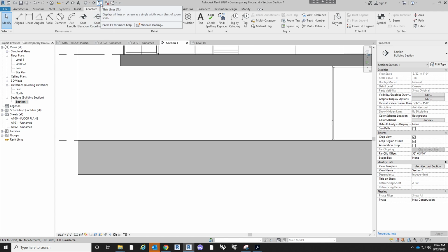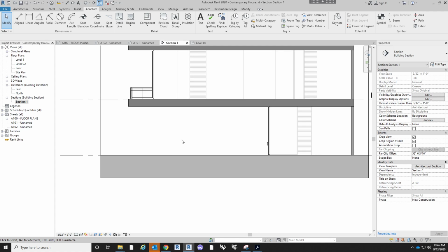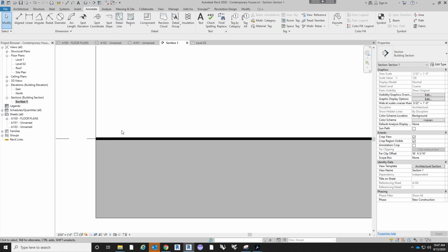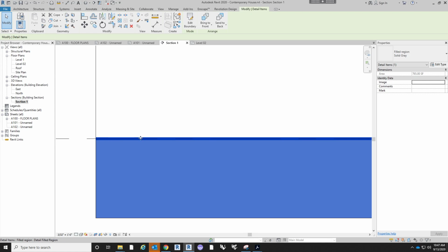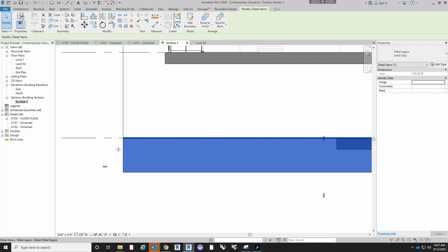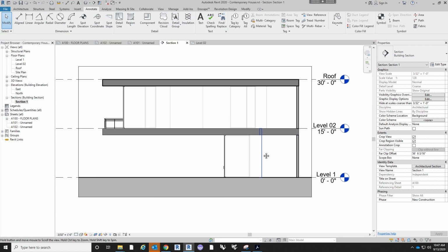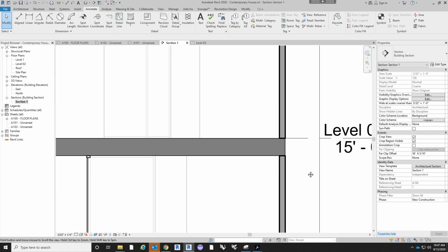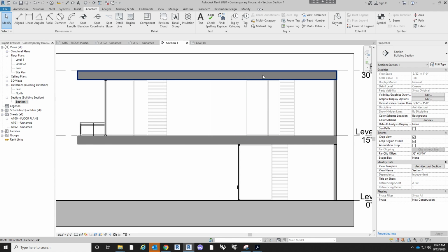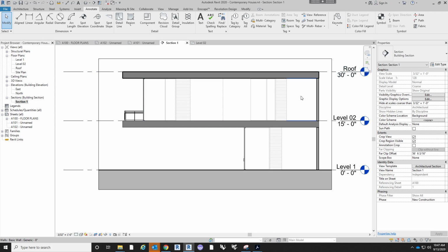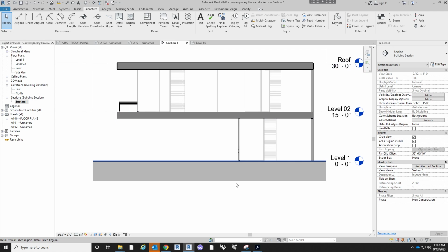the reason why we can't distinguish it right now is because we have our thin lines up at the top on to be able to distinguish between objects and have really nice crisp control over everything. But if we go up at the top to this thick line to thin line and uncheck that, you can see that the wide line that we just associated with the filled region is much thicker than the rest of the lines. And it also distinguishes the roof line from the floor line.